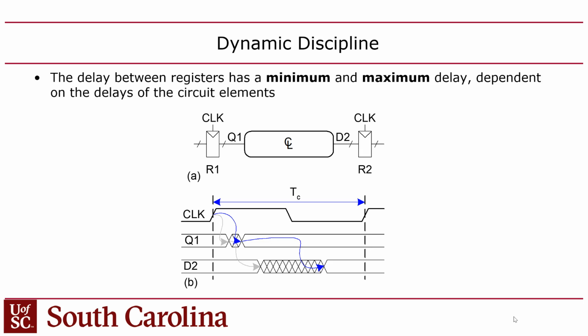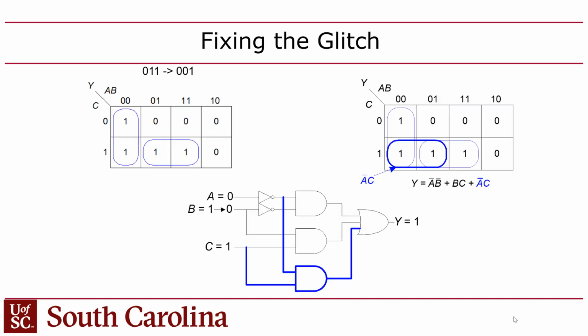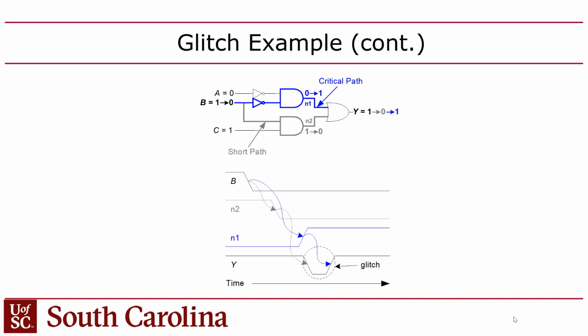Yeah, I know. And the bigger problem, and this is a problem I've struggled with my entire career, is this: let's say it doesn't run as fast as you want it to. Then what do you do? Well, that part's tough because it's going to tell you what the paths are that violated it. Whenever you generate a timing report, it's all going to be in terms of input and output paths, right? But these are paths that are in the synthesized circuit, not necessarily in your Verilog.